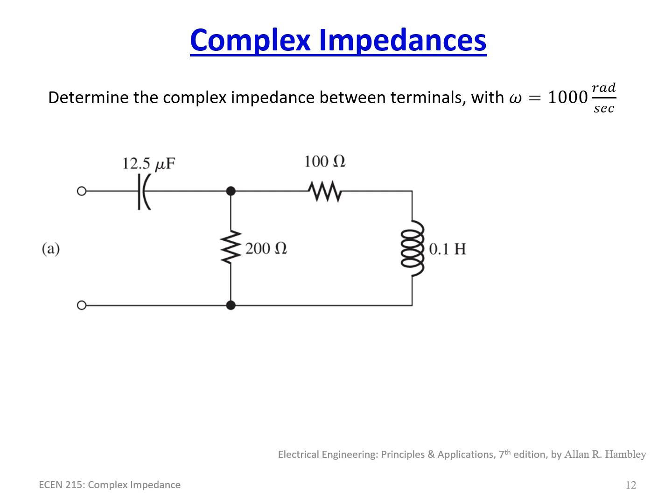Well, simply the first step is to convert everything over to its impedance. And remember, capacitors are 1 over omega C, phase shift minus 90 degrees, or also in the rectangular form, minus j 1 over omega C. And inductors are omega L at 90 degrees, or in the rectangular form, j omega L. So let's go ahead and do that for this particular problem.